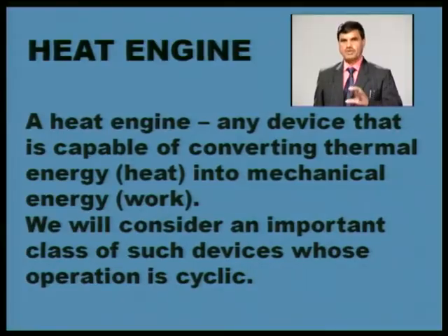Because it is low grade energy, the total conversion is not equal to the heat we have supplied to the engine. Always the work we receive from the engine is lesser than the heat we have supplied. Suppose we supply 100 kilojoules of heat to this internal combustion engine; we will never receive 100 kilojoules of work on the shaft.